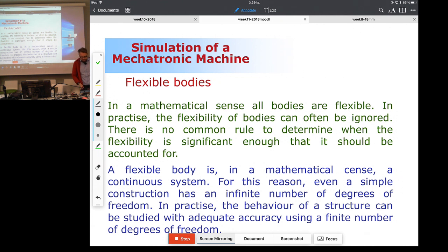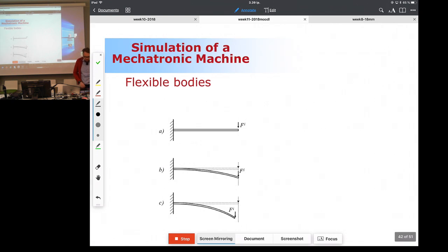But the extreme situation that I was referring to is related to the amount of deformation, which defines how we deal with linear or nonlinear deformation. Okay, this is important for you because when we look at the deformation, there are typically two sources of nonlinearities. The first source of nonlinearity is the relation between the displacement and strain.